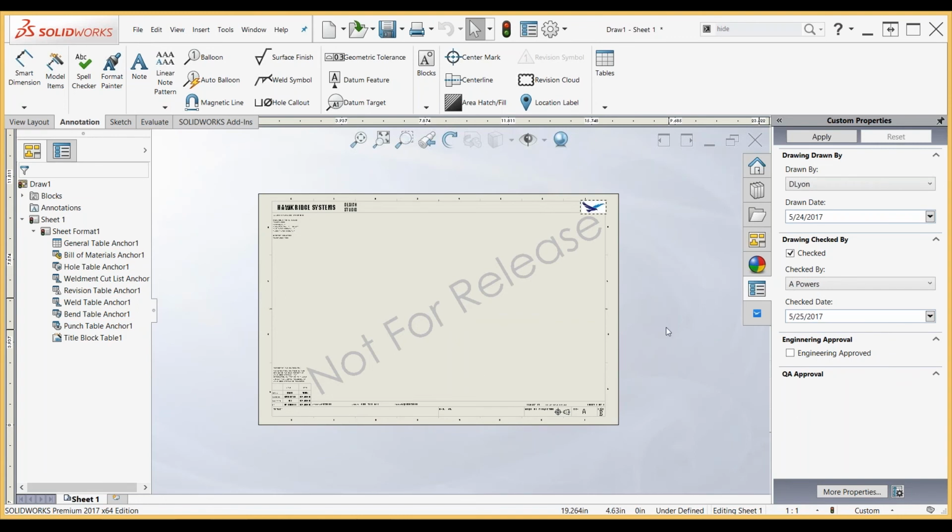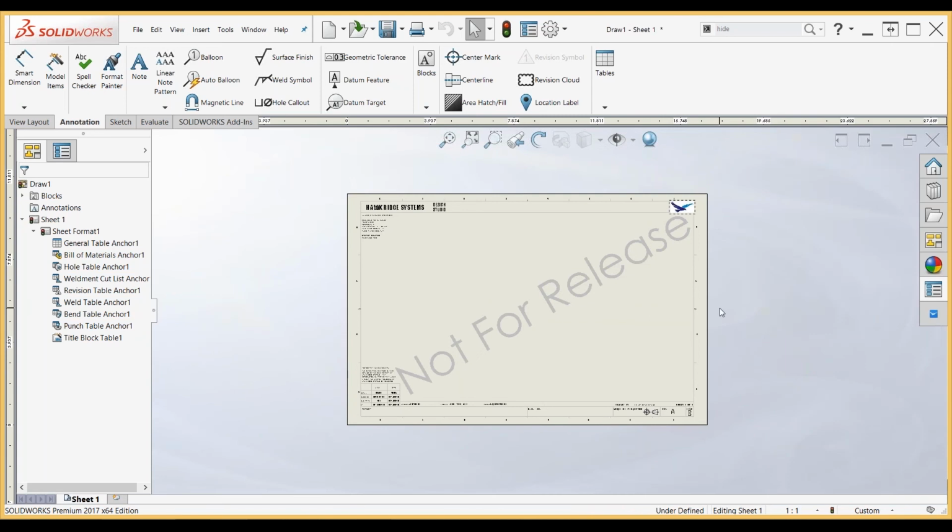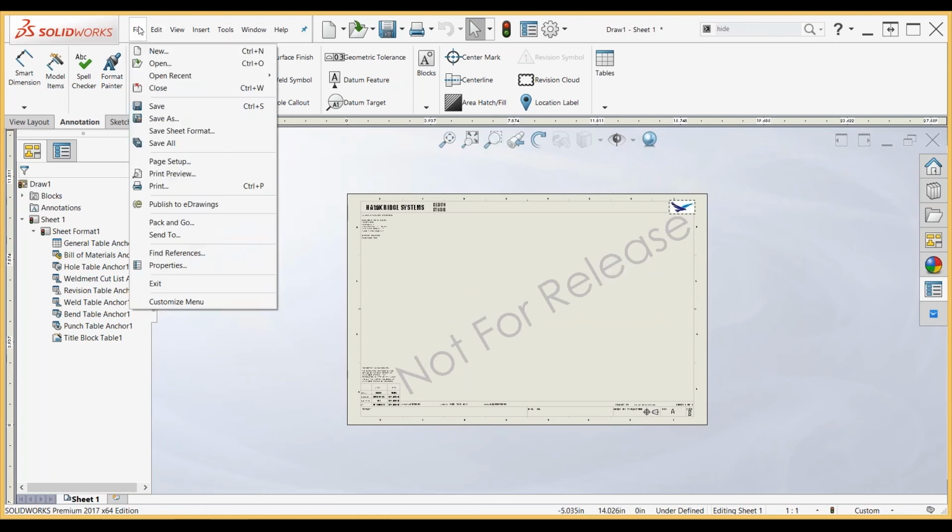So the things that you can save inside of the drawing template, aside from the sheet and the sheet format, is going to be all of your document properties up here. So that's your drafting standard. You can come in and play around with your units. You can change your precision, or maybe if you want to display it in fractions, things like that. But some cool options in the detailing section is the ability to auto-insert things on view creation.